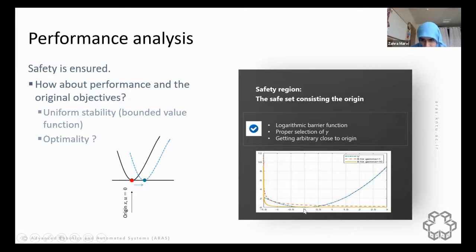We like to reach this point. So it's important that we have a function that rapidly damps as it gets away from the safety boundary. Here the function goes to infinity at our safety boundary, but it rapidly damps. So we can adjust it such that it becomes negligible in the rest of the area, and it just comes into play at the safety boundary. This is the reason that we use the logarithmic function.